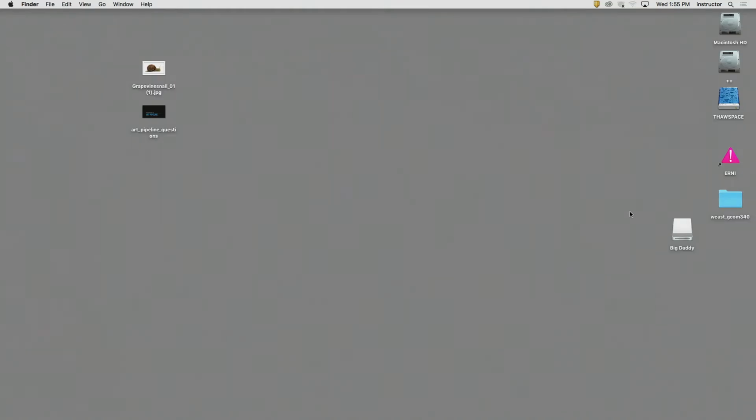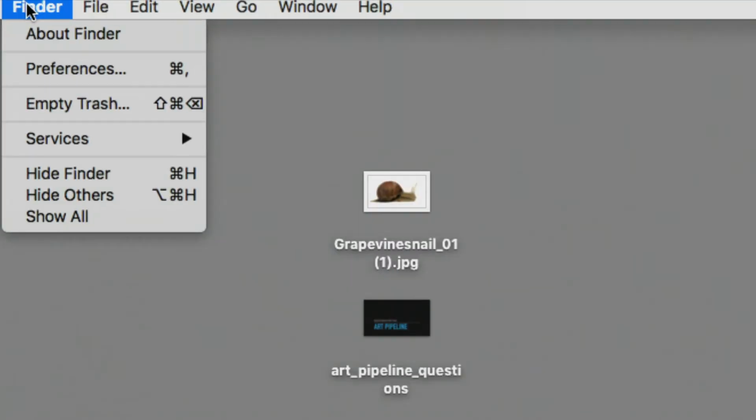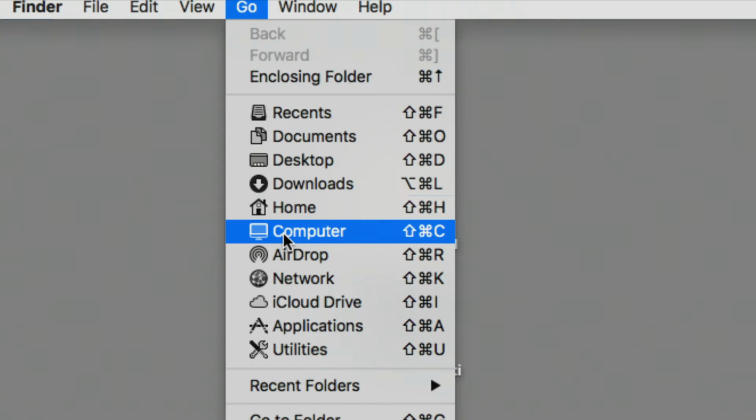One of the things that we can do to reset Maya and bring back all of its prefs, since it could just be a corrupted preference file that's stopping me from doing this, is that we have to go into the innards of our computer for a second. If you're in the OS Finder, the Go menu at the top of the screen will give you access to your library, but you have to hold down the Option key. They've hidden it from us because they don't want us to go into the actual library.